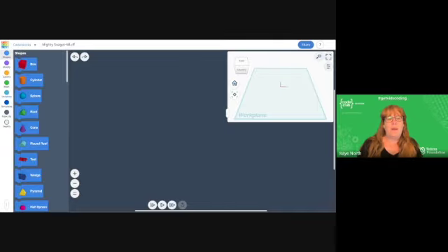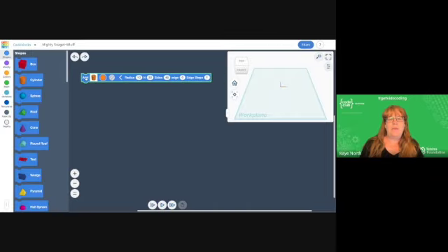To start off our project, we are going to add in a cylinder block and expand out the menu. It's important that we acknowledge that the solid is highlighted here because it is a solid shape. So the radius of our cylinder is going to be 13 and a height of 28. I'm going to change the sides from 48 to 64. This is just going to give us a much smoother finish, and we leave the rest the same.